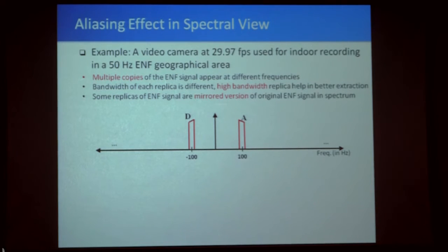Today's digital cameras also follow some of the traditions from the analog domain. When we try to squeeze our analog video into 6 megahertz bandwidth with both visual and audio, there's some compromise, and we also need to determine the right frame rate to make sure we have this kind of audio-visual multiplexing, as well as freedom from obvious artifacts and interference.